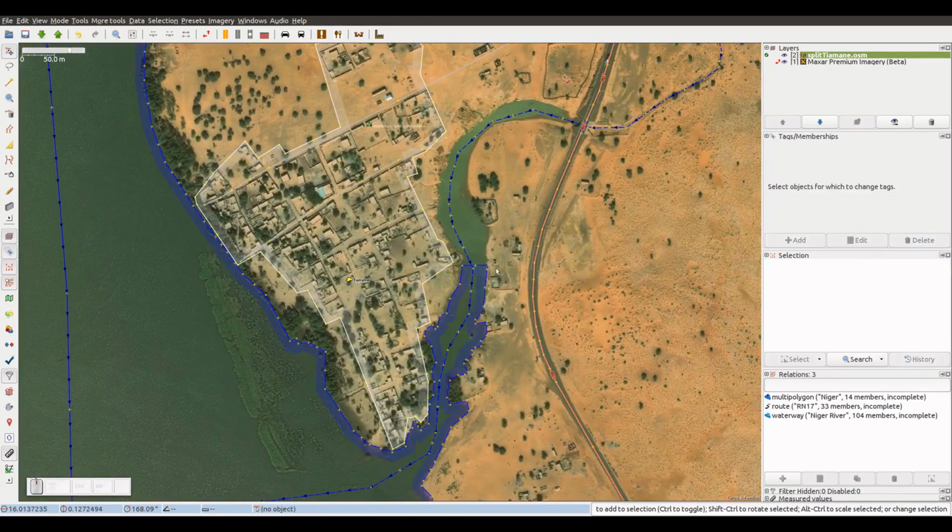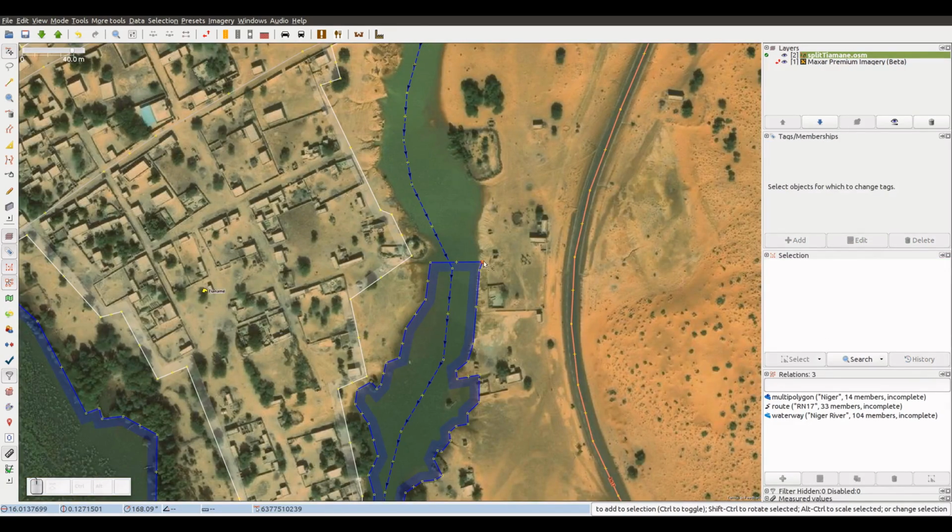We first need to select those 2 nodes of the way. Bear in mind that, if we wanted to split the way in only 1 node, JOSM would tell us that this is not possible, with this warning here. So, with closed ways we need to select at least 2 nodes. We select the nodes holding the Control key.